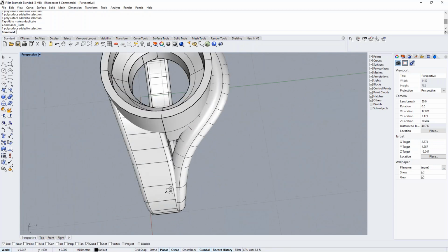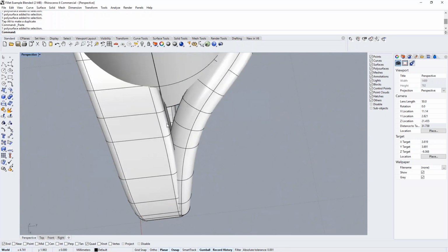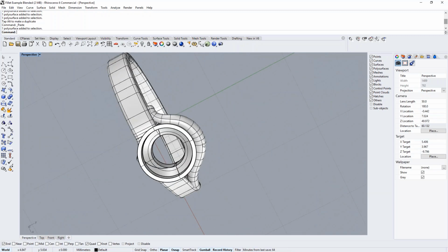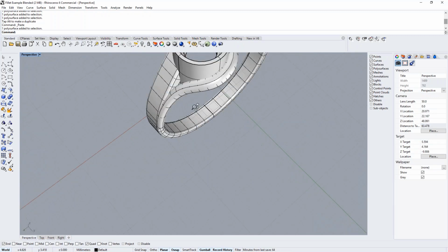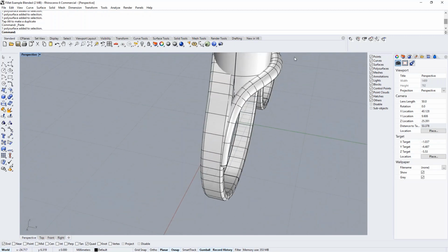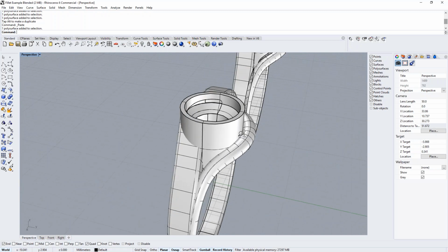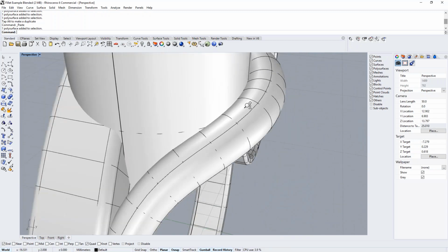But you can see right here, this is potential for huge problems in the casting process, right where this comes to a very sharp, acute angle. If you picture that in negative space, that's a knife edge. Metal's going to be rushing up here really fast, and some of that's going to break off, almost guaranteed. There's another little problem over here. And where these things meet too, because this is a pipe, a round cross section meeting a straight surface, this juncture too is problematic.